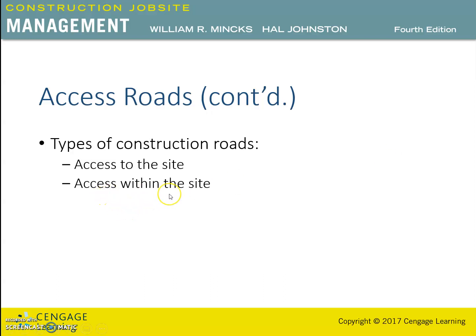with an access within the site, the access roads within the site are rarely designed or defined by the construction documents because they are the contractor's responsibility. Some occasions allow permanent internal roadways to be used during the construction phase, but these usually are constructed after the building and structures on the site.